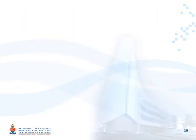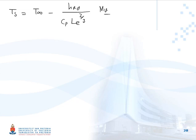So Ts is T infinity minus hfg divided by Cp Lewis to the 2/3, times Pv divided by M, times Pv,s minus Pv,infinity, divided by P, the pressure.